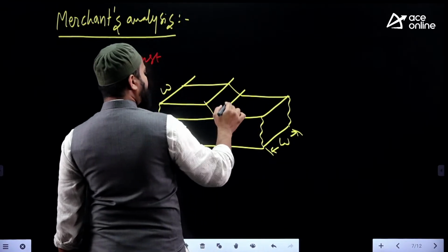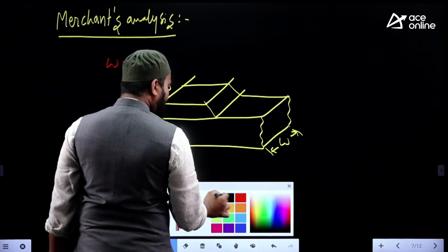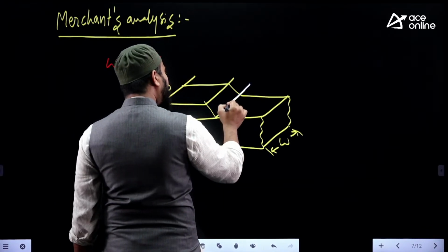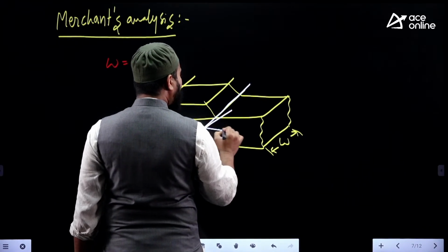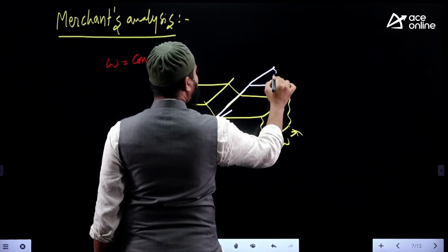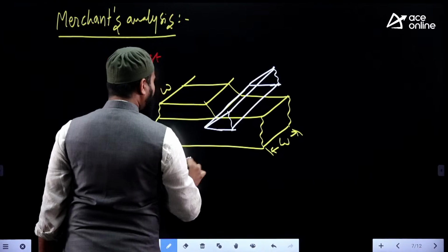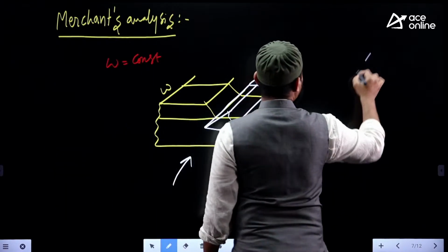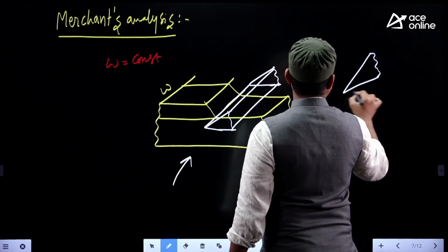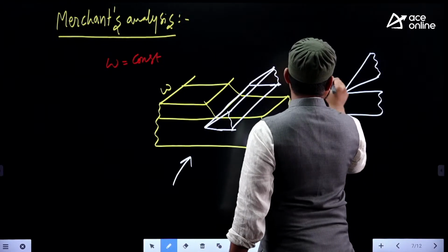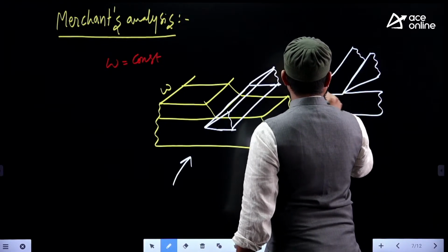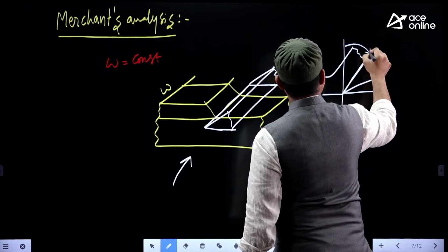And the tool whatever engaged here, the third experimental setup, takes the tool and workpiece in such a wedge format that if you make the projection of the tool and workpiece, we are again able to notice the same wedge shape of the tool with one angle, which we call the orthogonal rake angle.